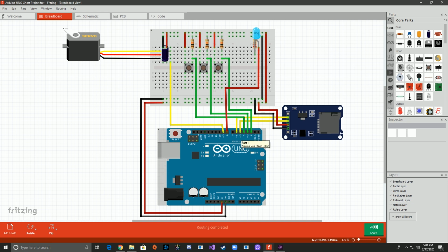So let's say we did that, right? Pin 5 would be transmitting. So it's going to come up and come to this bottom yellow wire here, which would be receiving. So we want TX to RX and RX to TX, right? That way we have a loop. So that pretty much sums it up for the schematic here. And we're going to jump next into the software and see how it works alongside this pictograph.